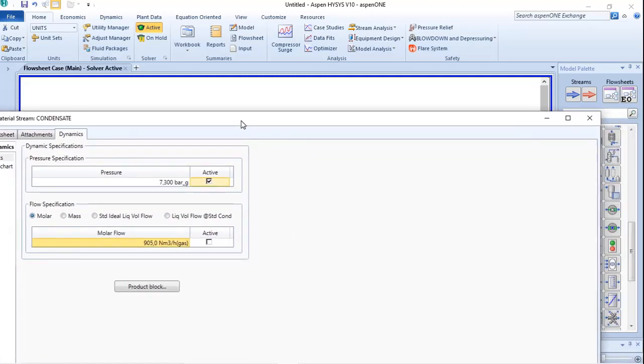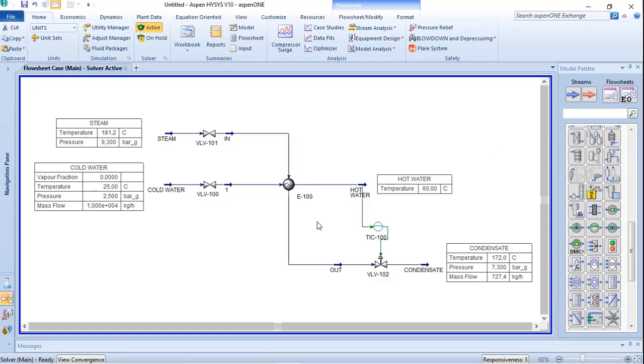during the dynamic simulation. Once you have your steady state simulation converged, you have the valves specified and you have your streams specified also in dynamic mode, and you can see that I specify only the inlets and the outlets of our process simulation. I will not change anything inside this because the valves here are the boundaries of my process simulation.